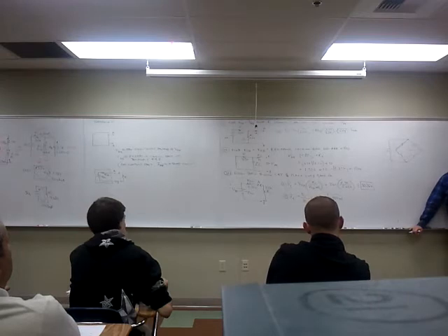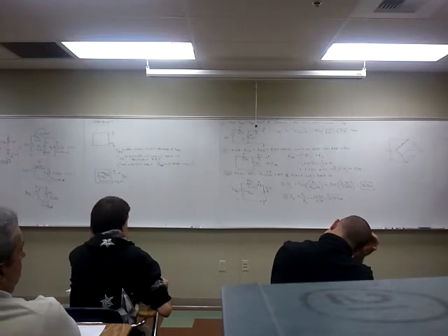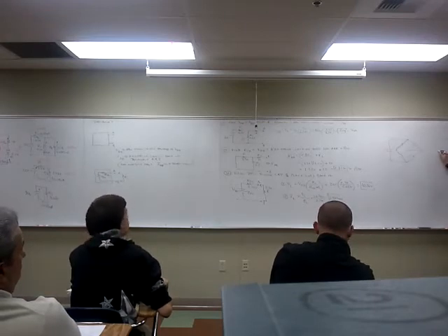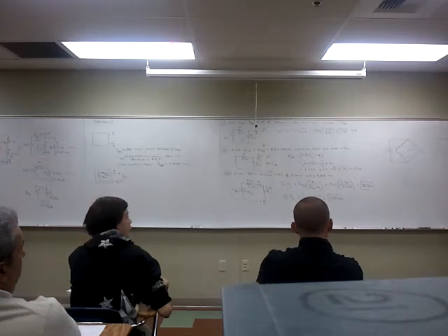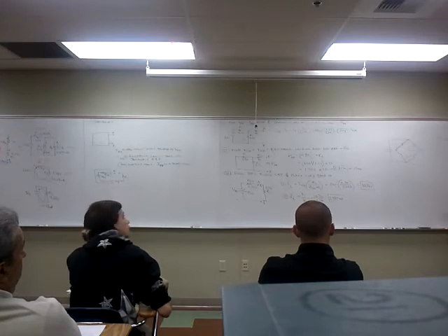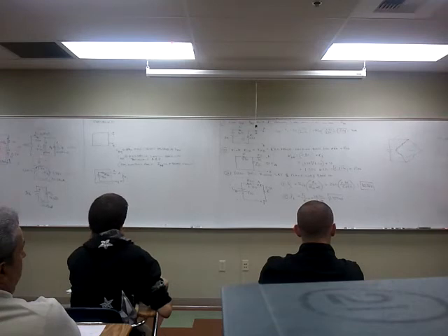So that's another reason. Then, look at this circuit that you've already done. The T with 2 power supplies. Which resistor do you think you'd want to remove to make this an easier circuit? Yeah. Look what it looks like when you take that out. Looks like a simple series circuit, doesn't it? Isn't that a hell of a lot easier to solve than when you had that resistor in the middle?